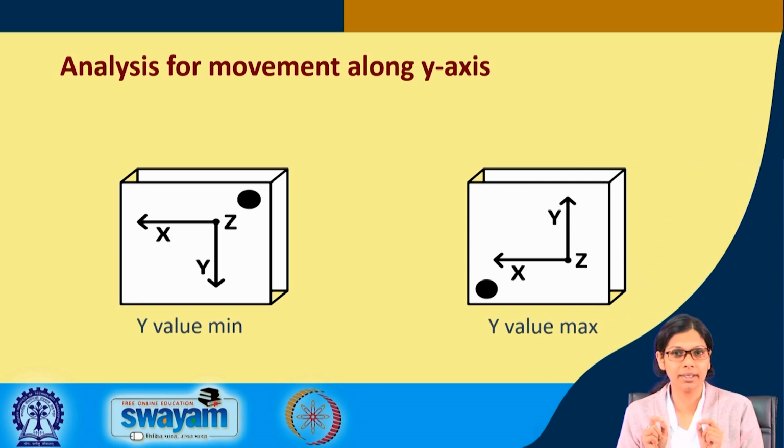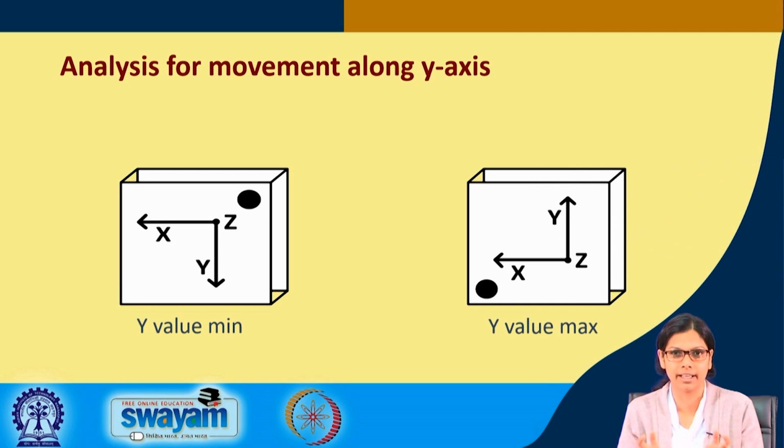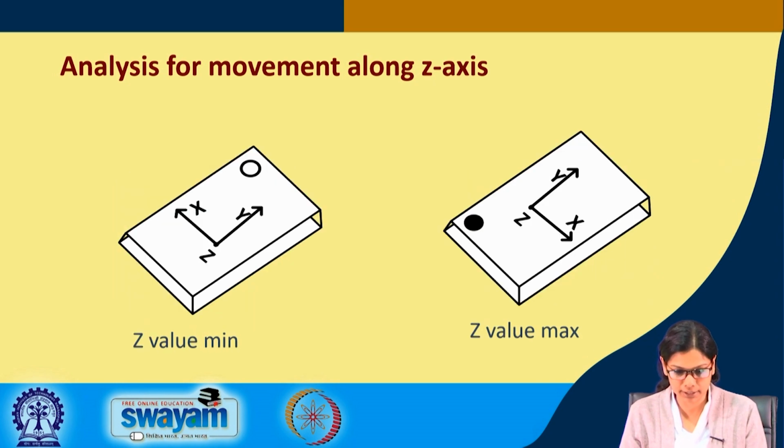Depending on this, you will be able to understand how you are holding the device, whether the device is straight, or it is vertically tilted to the left or vertically tilted to the right. So, different orientations of a device could be figured out from these values. Similarly, if you hold the accelerometer in this direction, then the z value will be minimum here and the z value will be maximum here. So, we will try this out with the STM kit.